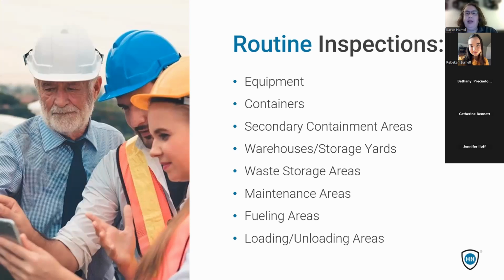And this may be outlined for some of these things within different regulations. So within your SWPPP, you may have intervals for inspections on storage areas, or you may have inspections for your fueling areas. If you've got an SPCC plan for large bulk oil storage and bulk fuel storage, you may need to do inspections on a weekly basis or a monthly basis. Look at the requirements within your plans. What do they say? If you don't have inspections for any of these areas for whatever reason, consider adding them.